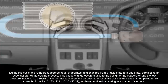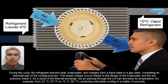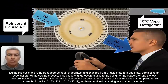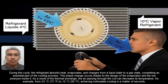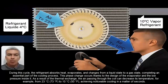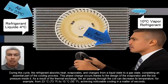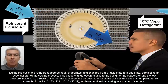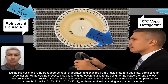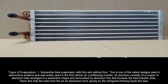During this cycle, the refrigerant absorbs heat, evaporates, and changes from a liquid state to a gas state, completing an essential part of the cooling process. This phase change occurs thanks to the design of the evaporator and the low pressure inside it. As a result of the thermal exchange, the air passing through the coil can decrease its temperature, for example, from 23 degrees Celsius, 73 degrees Fahrenheit, to 10 degrees Celsius, 50 degrees Fahrenheit, achieving noticeable cooling in a matter of seconds.